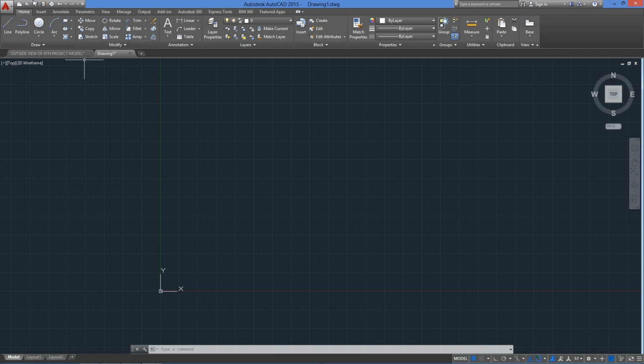Right next to it, we have the Quick Access Toolbar, which gives you access to some operations in just one click, like for example, saving, printing, opening and closing, and the always necessary undo and redo buttons. Next to this, we have the AutoCAD window title bar, which will include the name of your drawing and the version we're using. By default, CAD will numerate the drawings in sequence, 1, 2, and so on. And of course, we should always rename the drawing appropriately.